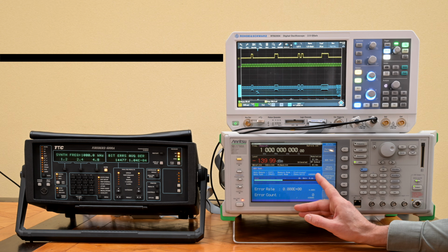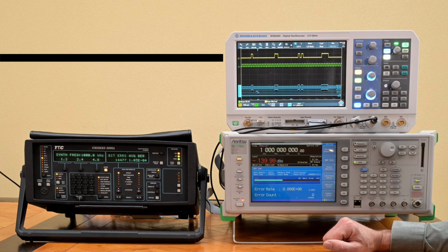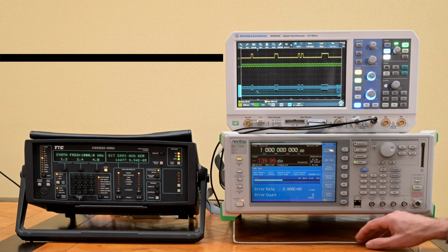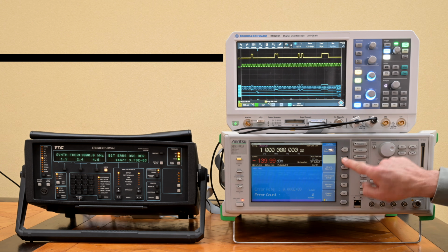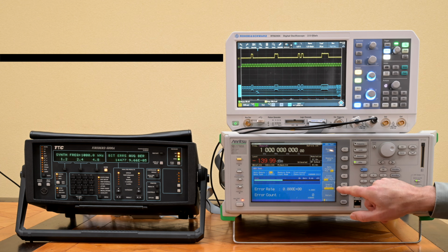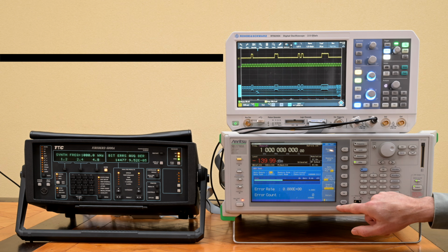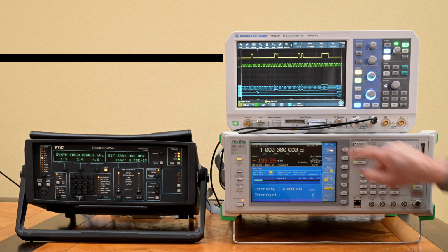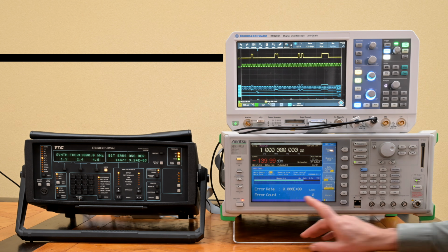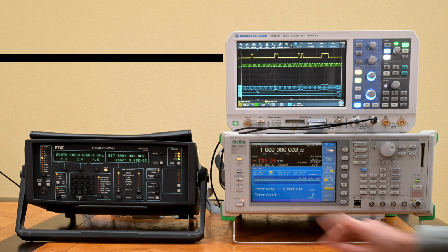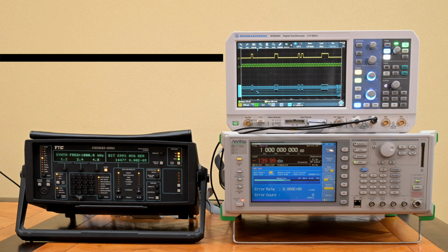The count mode is just telling us how many bits it will evaluate before reporting the results. So I think everything is properly set. I hope so. There's also some polarity and rise and fall, I guess it's all fine. So let's just start testing. Oh, we're good. And we're getting an error rate of 0 errors. It's always shown in scientific notation here. And right now we're not introducing any errors, so that should make sense.